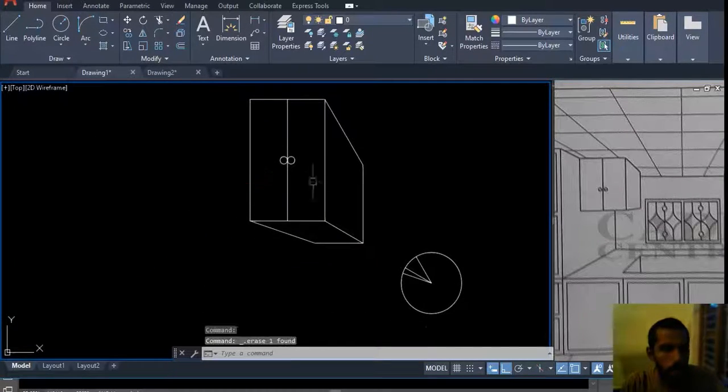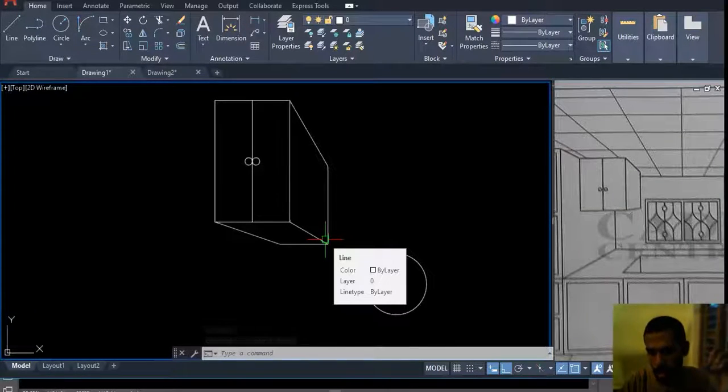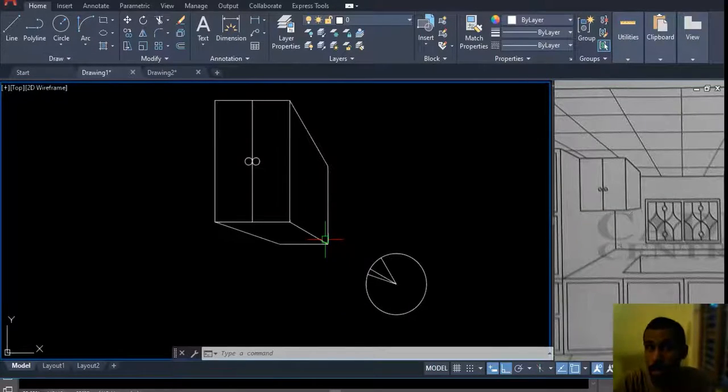Yeah, that is over. So probably that will be, you can see that there are chances for the object to be right onto the eye side of it, or right onto the top. So if that is on your eye side, there might not be a base right for this. So from the figure given in the right, that is right at your eye side, so there is no base shown there. But what I have drawn here is right above your eyesight, so obviously that will be having a base here. Okay, so you have to be a little bit vigilant about your position of the object and how you might be drawing this.